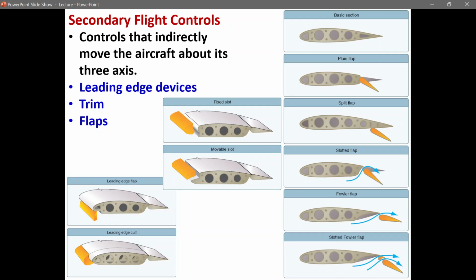You already understand the ailerons or the flaps at the end of it. They essentially do the same thing. We already understand that they are going to increase the camber, right? Ailerons work in a different direction because the two on different sides of the aircraft work in reverse, right? That's why you're going to see them roll. But a regular flap on both wings is going to move in the same direction, right? That's why it's just going to increase or decrease the lift and drag. So that's the difference between aileron and flap.